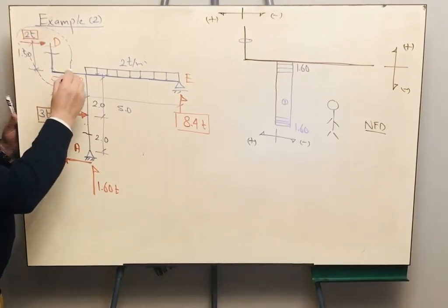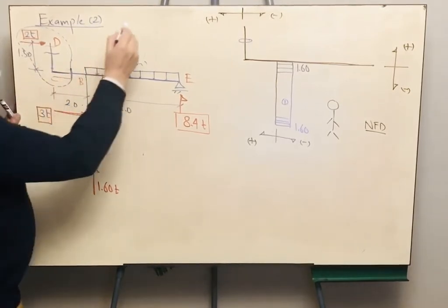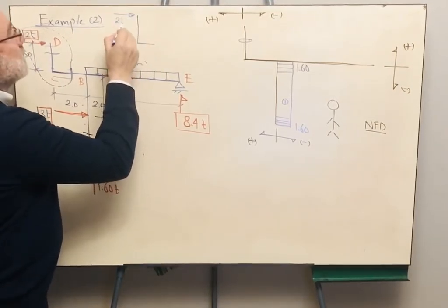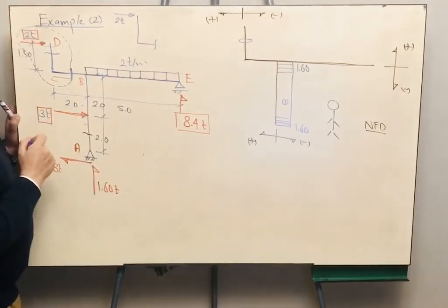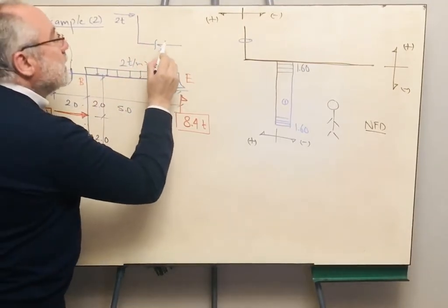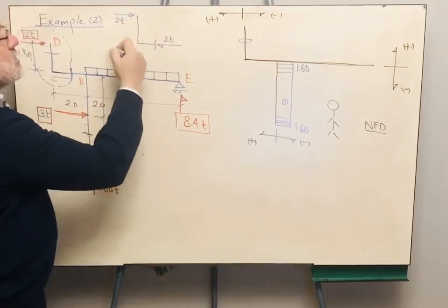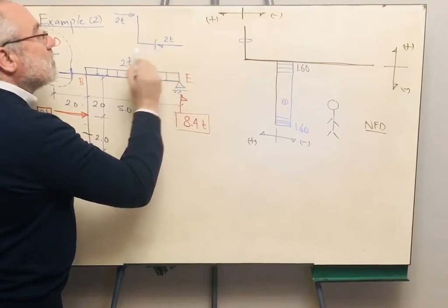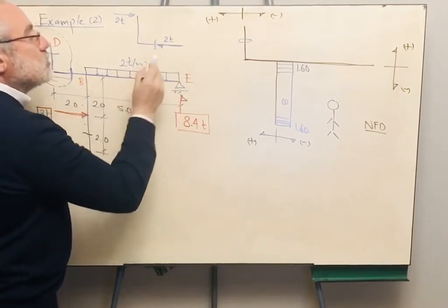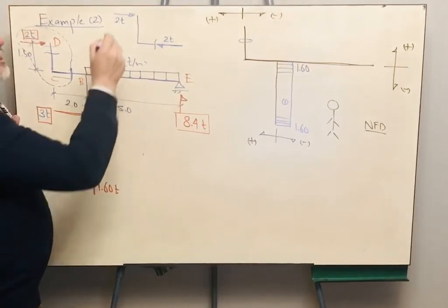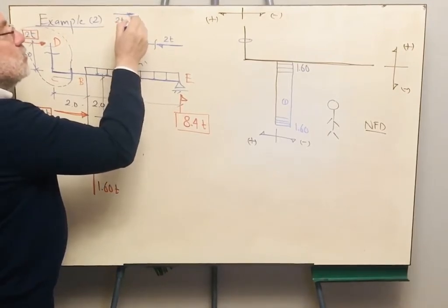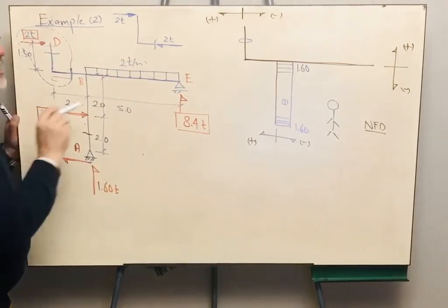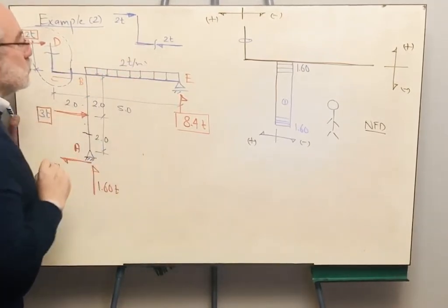Now, what will be the normal force in this side? In order for this part to be in equilibrium, here I have 2 tons, and here is my cut section. I should have a 2-ton force like this, such that sigma Fx is equal to 0. Therefore the internal force that appeared is directed towards the section, so it is compression. It is logical that this 2 ton is causing compression for this horizontal element. So this horizontal element is subjected to compression.